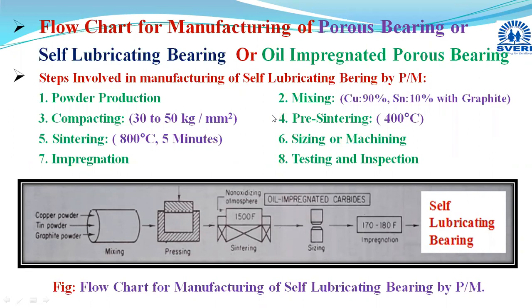And the reverse case will be like this: when the shaft speed decreases, the amount of frictional heat will decrease, and due to this, temperature and pressure fall. There will be a sudden drop in temperature and pressure, and due to capillary action, whichever oil is there on that shaft will flow back into the bearing. This is occurring due to the capillary action.